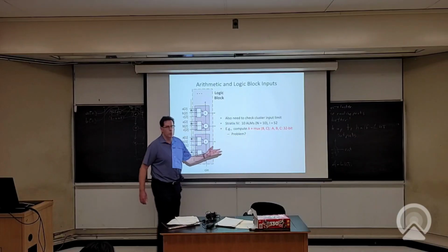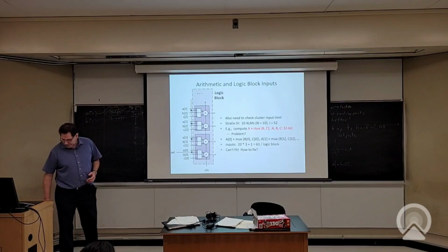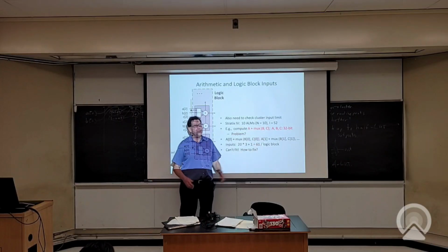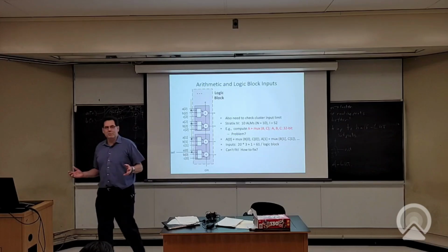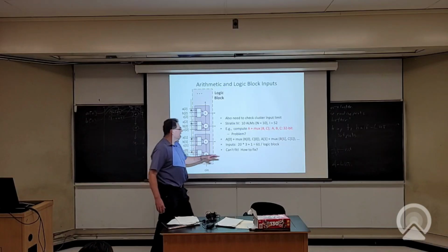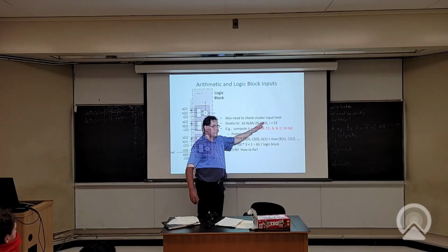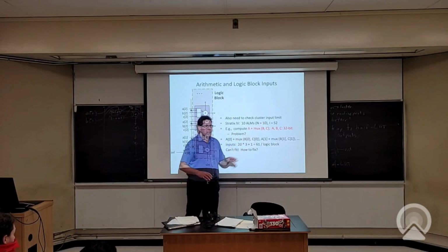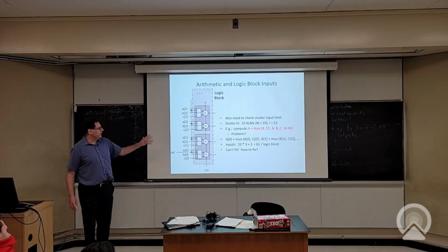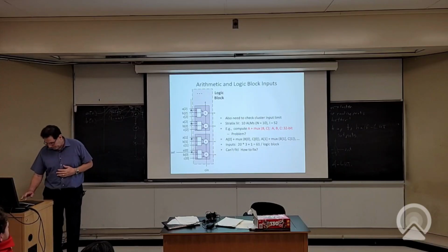Okay, that's 61 signals. So 61 signals is too many, right? I only built 52 signals. I don't want to build a whole bunch more routing ports just to make this work. It would be too expensive. So it's fine. I can just tell the CAD tool, don't do this, right? When you see this, these have to go in LUTs in a different logic block, and that's perfectly fine. But Altera came up with a clever solution to allow this to work, just for more efficiency.